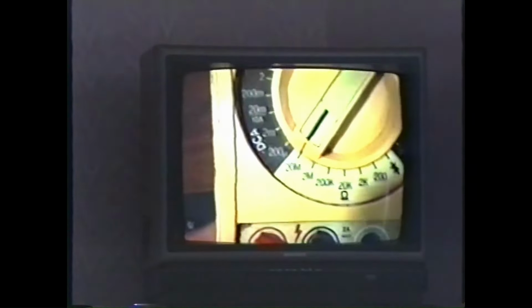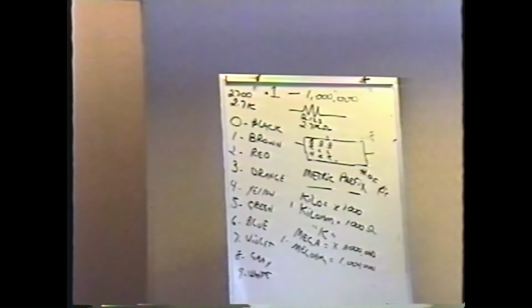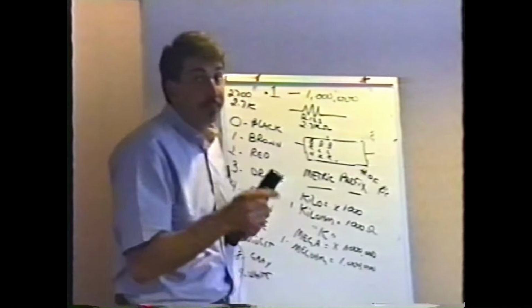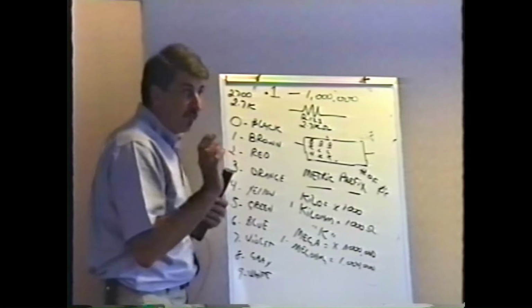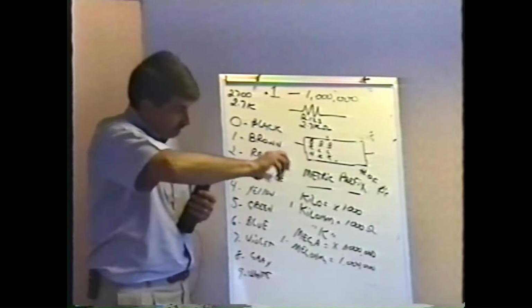You'll probably never use those ranges when you're working on games. As we'll see in just a little bit, when you start doing this resistor lab, the proper setting for your meter, if you don't have an auto-ranging meter, is to be as low as you possibly can without getting some kind of an overload indication.